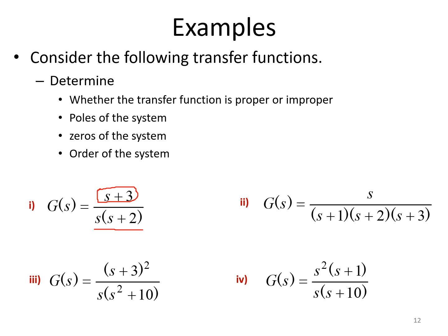Coming to the number of poles, if I equate s into (s plus 2) to 0, you can identify directly that one value s will take is 0, so s is equal to 0 and s is equal to minus 2. That means I have two poles, at s equal to 0 and s equal to minus 2.